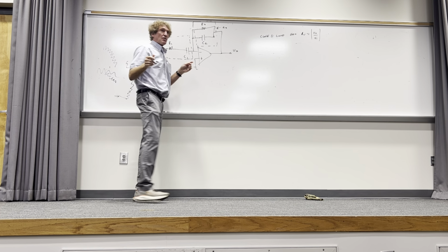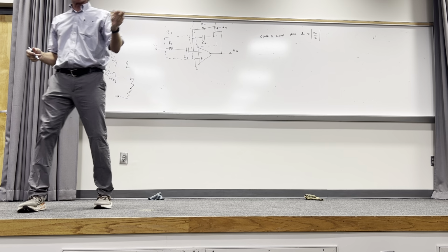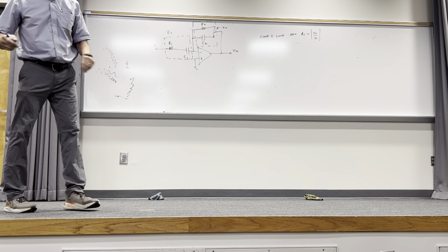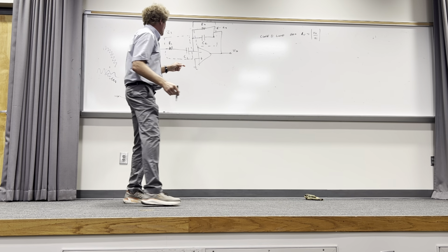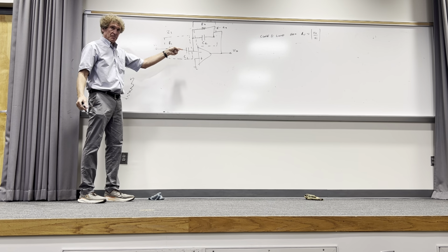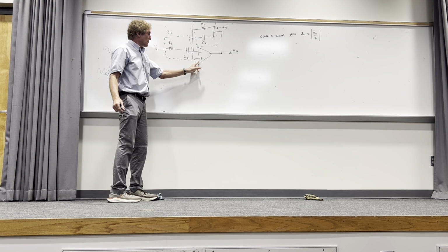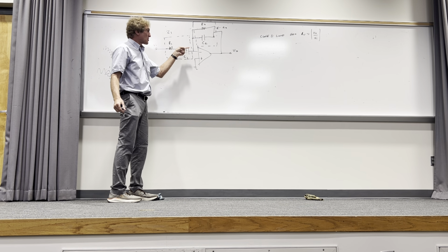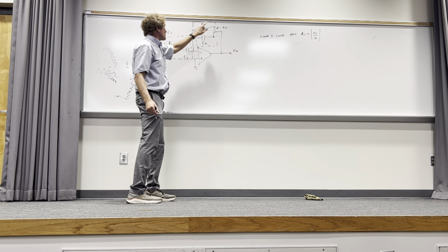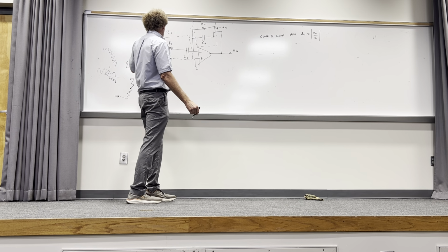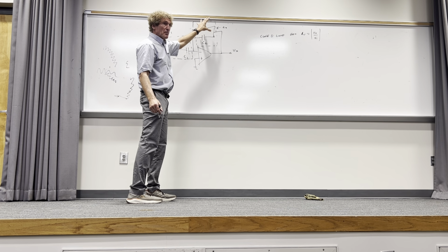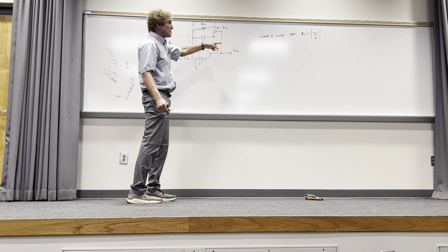Do you follow my thoughts as far as why I'm doing what I'm doing? All right, you follow me on this one? All right, so now, I could go through it. I could say well, the current here would be Vn over Z1. And because that's 0 volts there, no current in, all the current is going up here. So this voltage plus to minus would be I1 or Vn over Z1 times Z2. But because the output is inverted, it would be negative that.